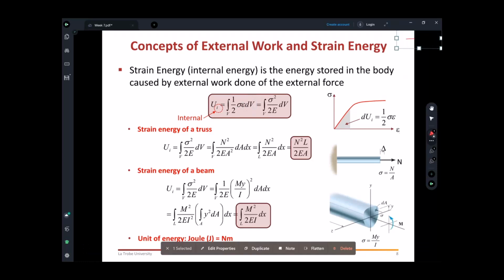Now what happens here, we keep the stress as it is, and for the strain, you know the Young modulus is stress over strain, which is basically the slope of this line. This distance, your stress, divided by this distance, gives you the slope, the angle. That is your Young modulus.